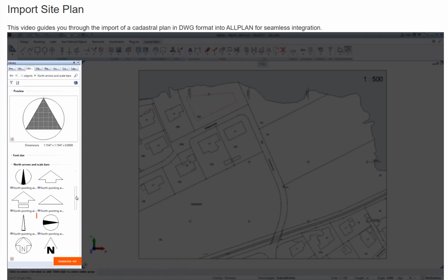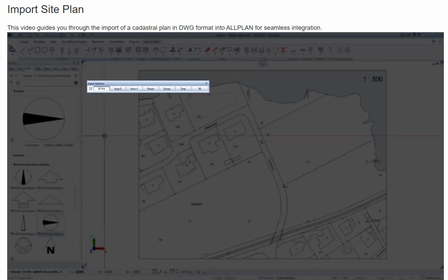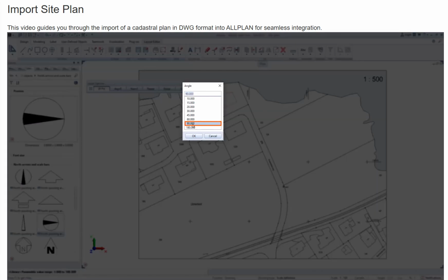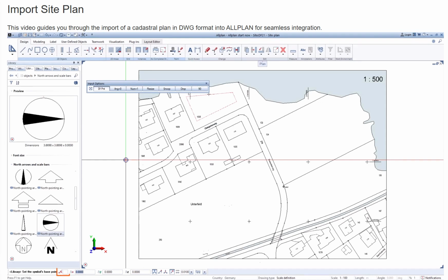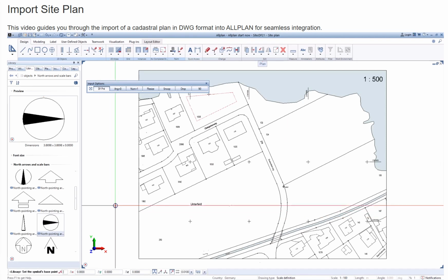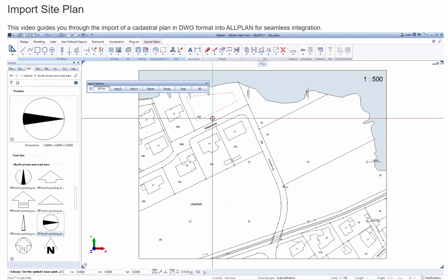By double-clicking the left mouse button in the preview window, the north arrow hangs on the crosshair. In the input options, select the default set-off point and set the delta angle for angle jump to 90 degrees. To rotate the north arrow on the crosshair, click in the dialog line in the input field behind library, symbol starting point, and then press the plus key on the keyboard once. The north arrow symbol is now properly aligned and can be placed in the upper right corner of the plot.